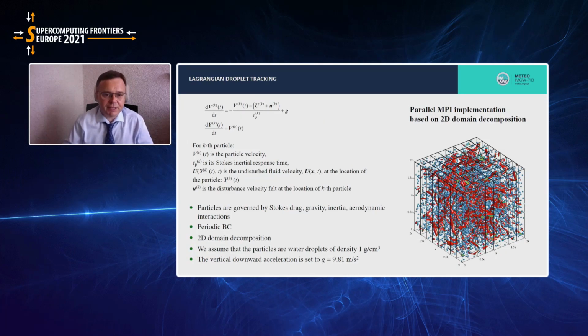For modeling droplet dynamics, we use a standard Lagrangian approach. Motion of droplets is governed by Stokes drag, gravity, inertia, and in some cases, aerodynamic interaction. We again have periodic boundary conditions, and we use physical values for density and gravity.